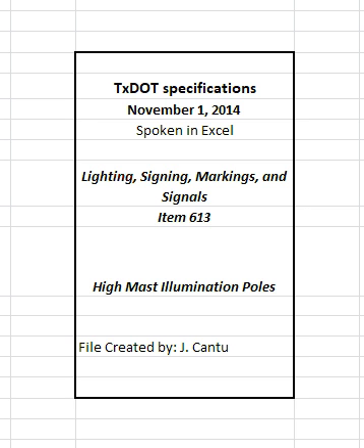Stake and install high mast illumination poles as shown on the plans. The engineer may shift the assembly locations, within design guidelines, where necessary to secure a more desirable location or to avoid conflict with utilities. Use established industry and utility safety practices when installing poles located near overhead or underground utilities. Consult with the appropriate utility before beginning work. Prevent scarring or marring of the poles.